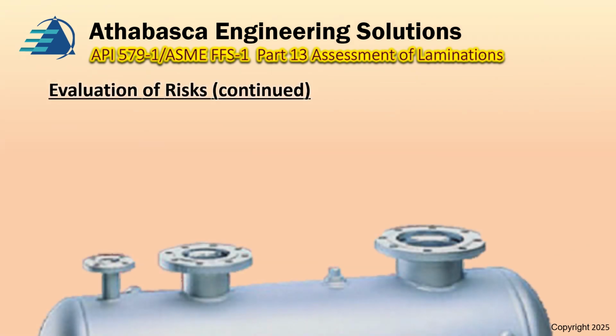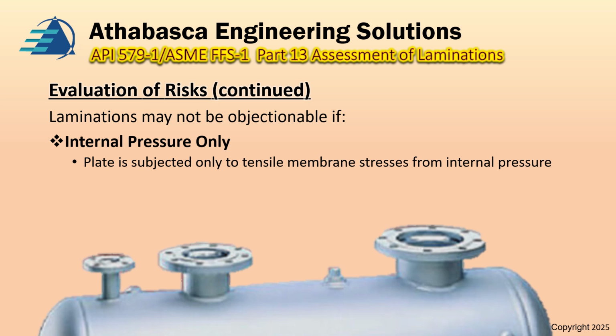About the evaluation of risks. The laminations may not be objectionable, or an issue, if, for example, it's internal pressure only and the plate is not subject to tensile membrane stresses from internal pressure, or we're far away from structural discontinuities.